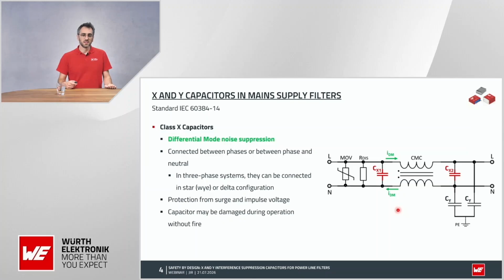And the X capacitors, in this case, we have one before the common mode choke and one after. The X capacitors provide a low impedance path for this current to flow. X capacitors also provide an important safety function because they are able to handle some surge voltage, and this is all defined in the standard, how much.